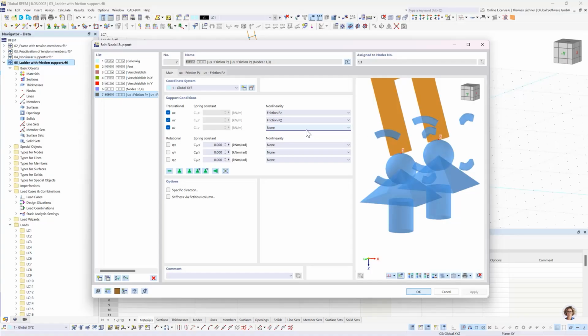It's also a hint for the future, like you try to model your system as simple as possible for your investigation. So you don't need to apply every nonlinearity there is, because it's just making things more complex. You just try, okay, what do I want from my model? And with this thought, you're gonna start modeling. So there's no sense in over modeling, I would say. Just model what you need and nothing more.